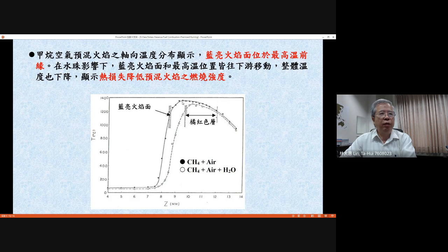This is the so-called flame temperature. But in this case, I cannot say this temperature is the adiabatic flame temperature, because in the experiment we use the quartz as the stagnation point, and the quartz absorbs heat in the downstream layer. You can see the temperature start to decrease in the downstream region, up to the quartz plate. The solid circles represent a typical flame temperature for a given premixed flame.